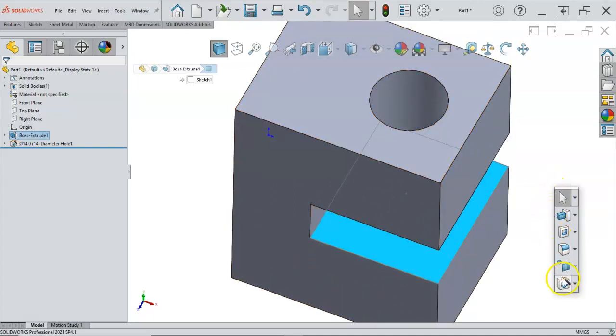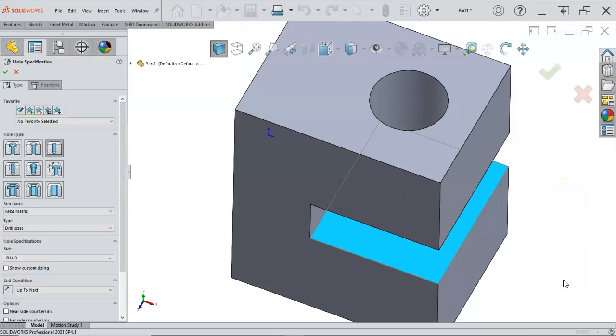All right, so the M12, clicking on the face or rotating over and clicking on the face, we can go to the S key, pick the hole wizard, and then we want to go with a straight tapped hole. Shouldn't really matter tapped hole or bottoming tapped. A lot of times I'll just leave those because if it is a blind hole, we'll have a little better sense of that geometry.